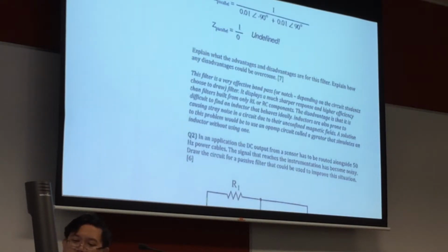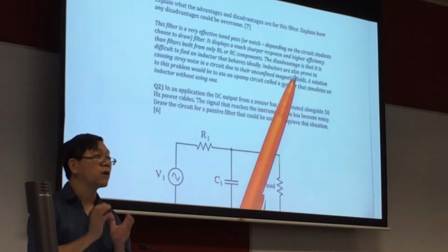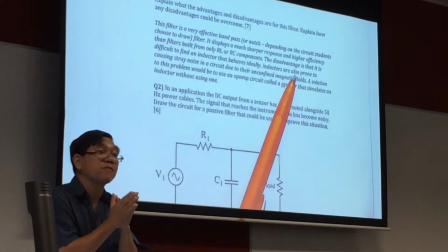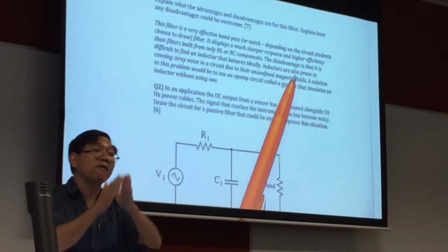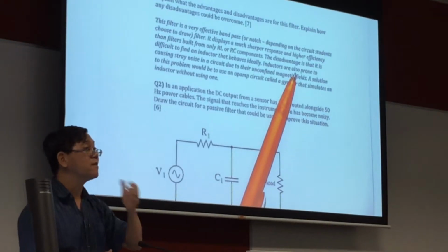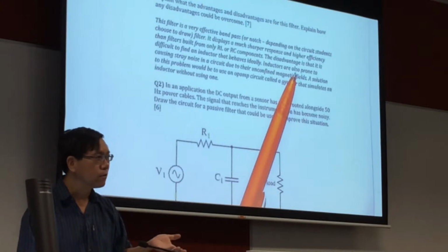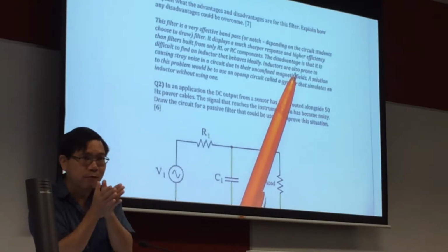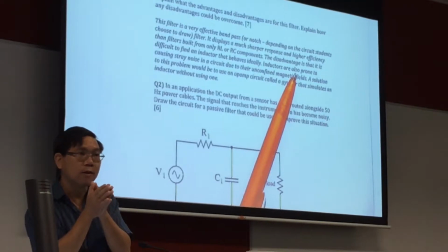So what is the advantage? The advantage is because it is only at one particular frequency that it nearly cancels. So it becomes a very narrow selective bandpass filter. Okay? Now if your answer presented is a notch filter, for example, then what happens? It becomes a very narrow selective notch filter. Is that clear? You understand?